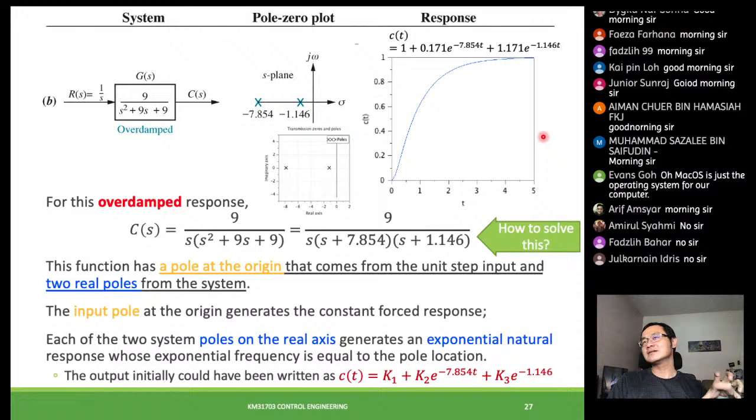First order, straight up and no oscillations at the end, okay? Whereas for the second order, you have this small curve, and then they may start to oscillate, okay? But sometimes, because we are putting a lot of damping over here, we call that overdamped, then it doesn't oscillate, okay, but it still behaves like a second order, right?